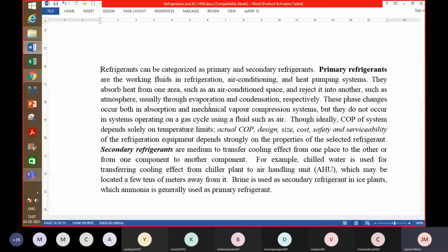So now you know about the vapor compression refrigeration system, which is the most common or most dominant system in the field of refrigeration. In this system, on one side, when the heat is absorbed from the space or the product, there is evaporation of the refrigerant, and on the other side, the heat is rejected by condensing the refrigerant.